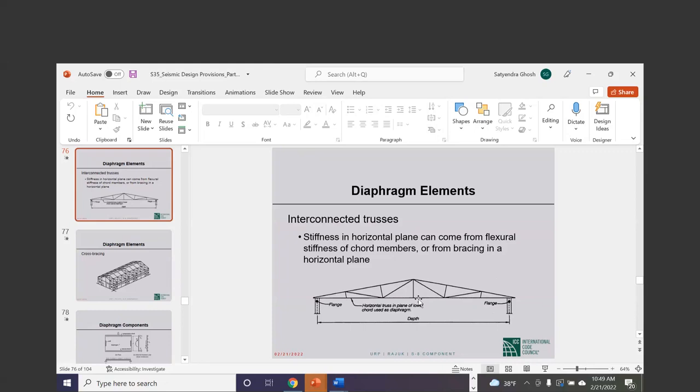We would appreciate if you can discuss the relation between drift and displacement. It's very simple. I have discussed it many times. Deflection is deflection, okay? If you are talking about floors under lateral load, how much does the floor move sideways? That is deflection or displacement. The drift is interstory displacement. Drift is deflection at the top of a story minus the deflection at the bottom of the same story. That's very important, okay? Deflection is for a floor level, drift is for a story.